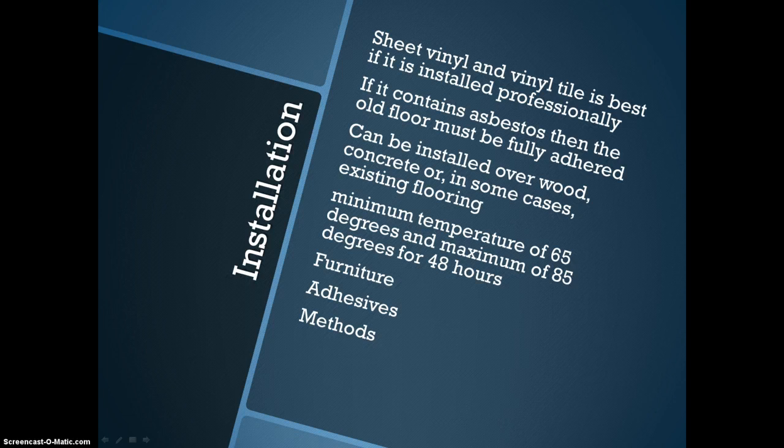The walls should not be used as a starting point, and asphalt tiles and adhesives eat through vinyl, so they must not be covered. If furniture is not equipped with the proper load-bearing devices, then indentations will mar the vinyl surface. You also need to make sure to follow the manufacturer's recommendations and use the appropriate adhesives, because use of the wrong adhesives can cause discoloration to the vinyl.